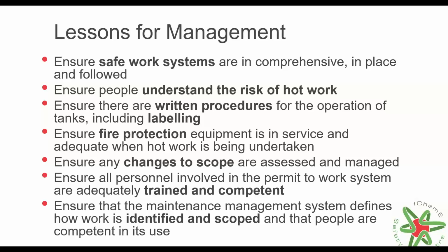And to ensure that the hazards and controls are identified on any permit issued and that the workers understand those hazards and controls. And lastly, that all isolations are documented, and management should perform a line walk to verify this, because when we're doing hot work, we are talking significant hazard activity.